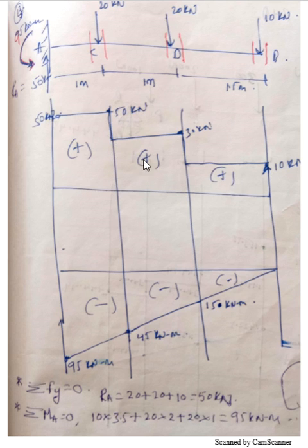It is very simple. Now for plotting the bending moment diagram, consider only one section, no need to consider both sections. If I consider this section at this point, there is a force to the right hand side but the perpendicular distance is 0, so I am going to consider the moment at this point as 0. Now consider this section, coming from the right side, there are two forces, one is this 10 kilonewton and the other is 20 kilonewton. But because of this 20 kilonewton force, there is no perpendicular distance, so the effect of this will become 0, because moment is force into perpendicular distance. Since distance is 0, this effect will also become 0.